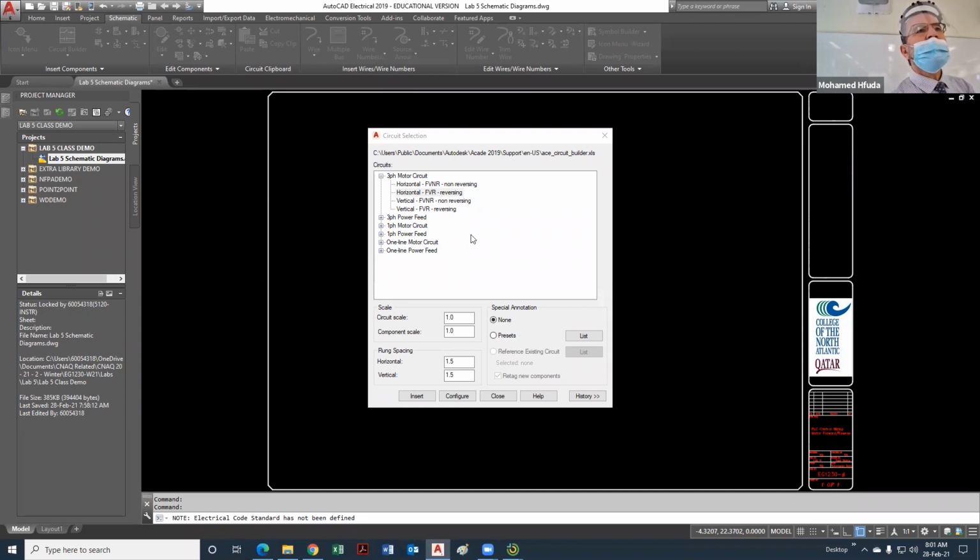It's called full voltage starting. Are you guys taking notes? Where are your notebooks? When you say this motor is full voltage, you mean it's full voltage starting. There's another name for it. In industry, it's also called DOL. What's DOL? Direct online. You need to know it, like one plus one equals two. Direct online, DOL.